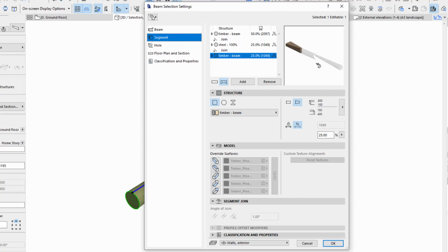So you could have a tapered end or a different thickness end. You might have an exposed rafter internally that's 200 deep, and out on the eaves you only want it to be 100 deep. So we can cut down an end segment and trim that, or we can have different scenarios where we've got perpendicular ends or vertical ends, or even different tapers on the ends. So we can set up some favourites for different scenarios as we come across those.